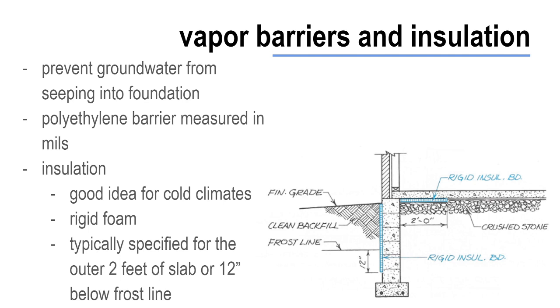It's placed against the foundation wall, up to where that haunch would be for your slab footing. It typically only has to go in about 2 feet from that foundation wall. The heat of the building itself can help keep the frost from penetrating more than 2 feet into the perimeter of the floor slab.